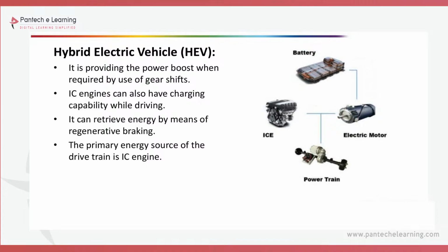For example, if the battery is 12 volt, the generated voltage is 4 volts. But to charge a 12 volt battery we need to supply 13 to 14 volts, which is higher than the battery voltage. Generating 3 or 4 volts is not enough to charge the battery, but theoretically it can be possible. That is regenerative energy, and testing is under process.